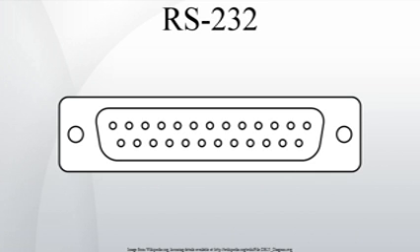An RS-232 serial port was once a standard feature of a personal computer, used for connections to modems, printers, mice, data storage, uninterruptible power supplies, and other peripheral devices. However, the low transmission speed, large voltage swing, and large standard connectors motivated development of the Universal Serial Bus, which has displaced RS-232 from most of its peripheral interface roles.